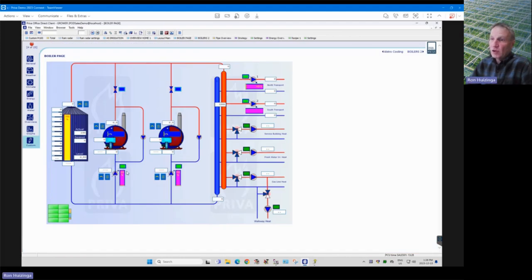We always call this the fill pump on the system. A frequency drive has an arrow through it in the drawing, which means it has a frequency drive on it. So normally this pump always has a frequency drive. There are different designs here. So this can sometimes be called the boiler loop pump or shunt pump. There are different names people call this pump, but basically it's a boiler loop pump. It pumps from the hot side of the boiler to the return side. And in different engineers' drawings, I see it called different names.